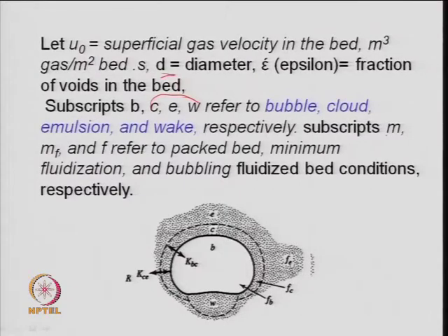So, when there is no velocity of the gas or very low velocity of the gas, the bed is stagnant, solid particles, there is no bubbling. But when you increase the velocity, now the bed starts bubbling. So, there will be more and more void in the bed. These are the different terms used.